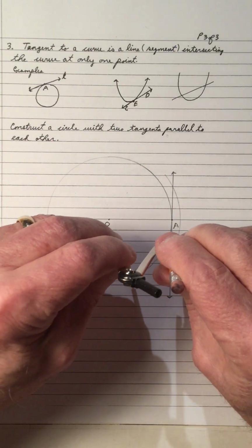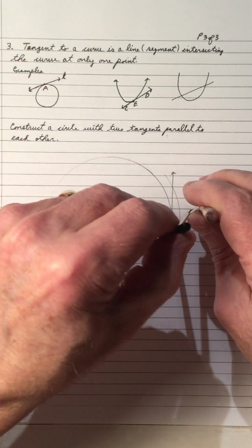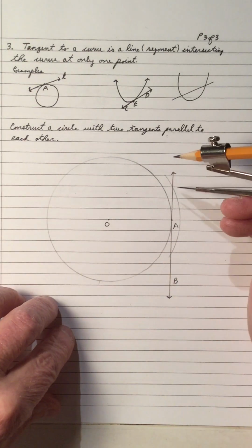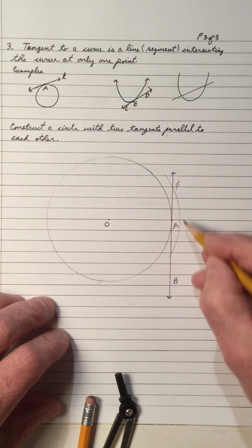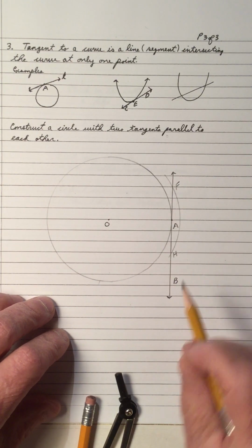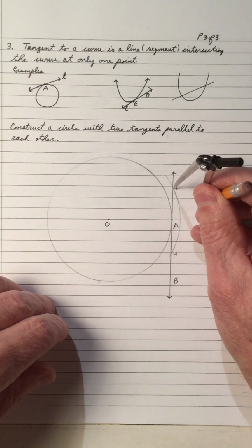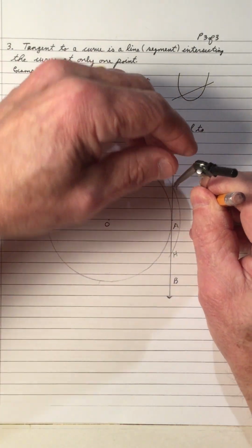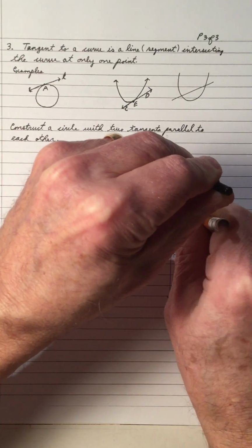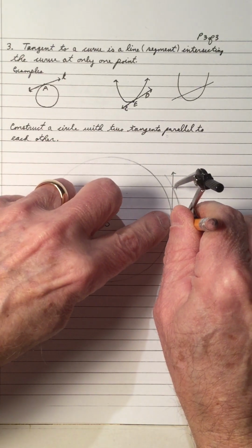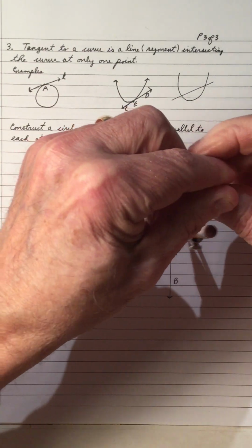Then we take our compass, and we can just get a certain distance. Remember, the distance got to be more than half of the length of this segment. So if I say this is F and this is H, the radius of the compass got to be more than half of FH. So there's F, and let's open it. There we go. More than half. Half, probably, let's say half is A, so let's open it up more. Here we have it. So we make an arc.